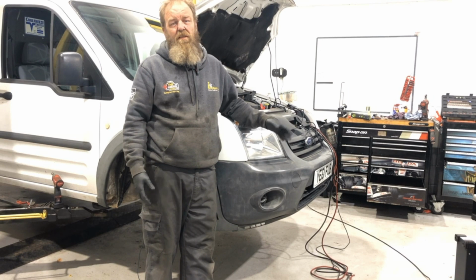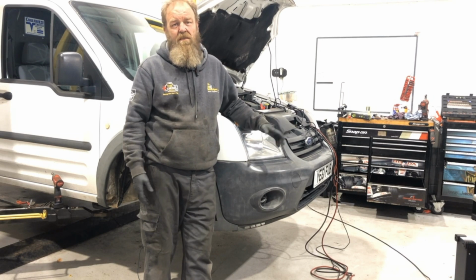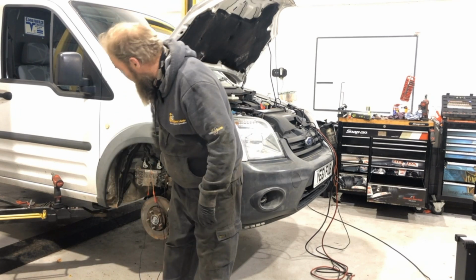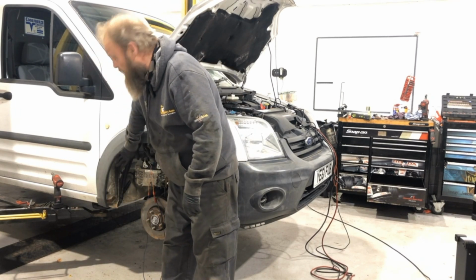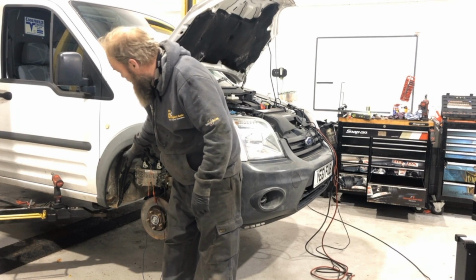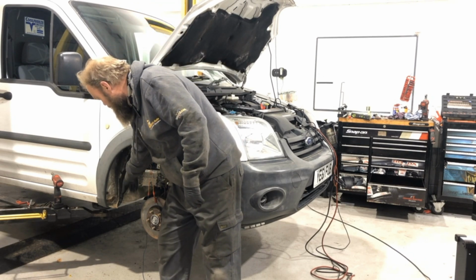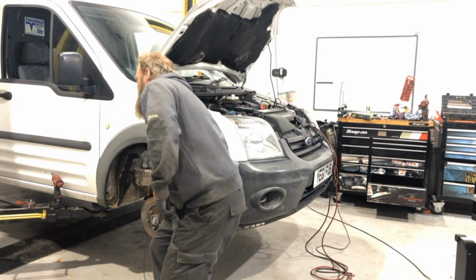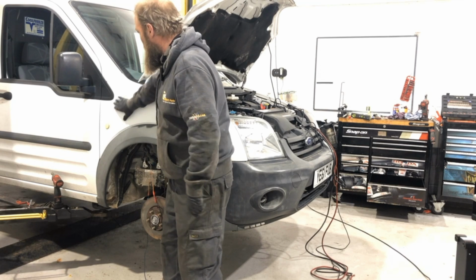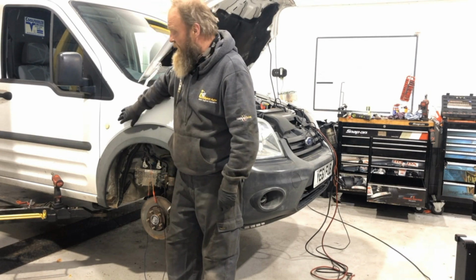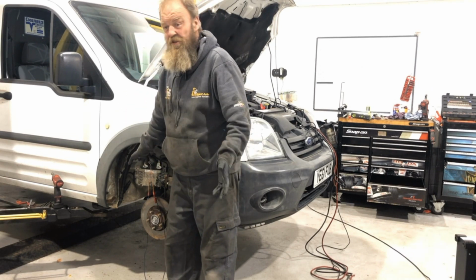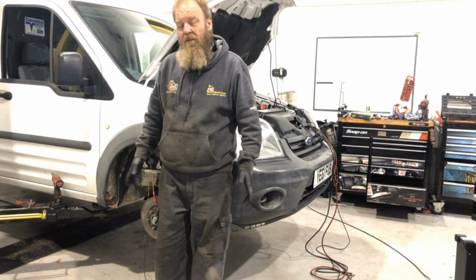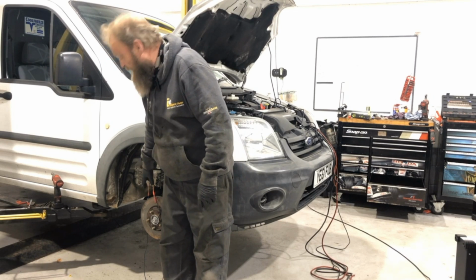Went to the crank sensor, checked the plausibility of the crank sensor, it was good. And then when I went to the engine ECU, I realised that the wheel arch liner, which lives in here, was all broken. And there was only a very small amount of it left just behind the wheel here. Now the engine ECU, as you can see there, lives up the back of this wing at about this position here. And as you would have seen when I was down there testing it, it's pretty cruddy and crappy. And it was actually worse than that because I've cleaned it up a bit.